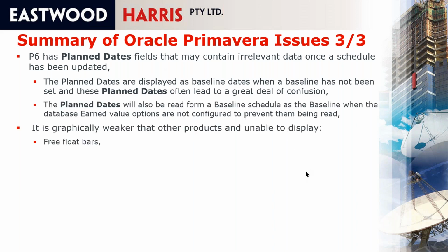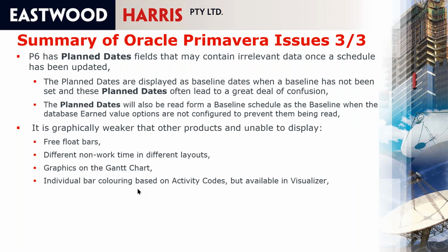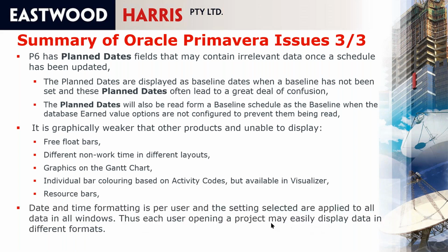It's graphically weaker. It's unable to display free float bars, different non-work time for different layouts, graphics on the Gantt chart, or individual bar coloring based on activity codes, but this is available in Visualizer. Resource bars, and date and time formatting per user, is selected and applied to all data in all windows. So when you set your date and time formatting, that formatting is displayed everywhere, which honestly makes it very difficult because you're going in and out of user preferences all the time in P6 to change your date and time setting to suit what you're doing.